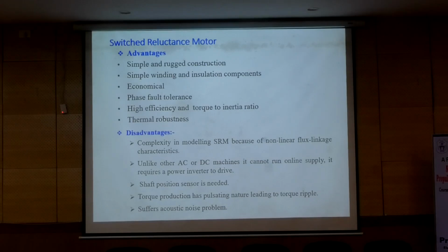And because of this switching operation, there is also a large amount of noise. If you compare the noise behavior of the SRM with the other counterparts, this produces a lot of noise, because of the high torque ripple behavior.